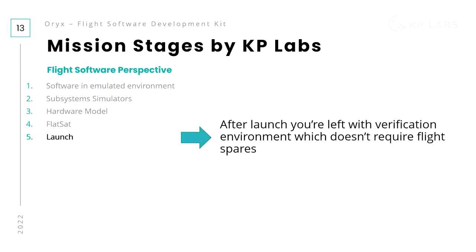So a very common approach is to have flight spares, but this is a very costly thing to do. Most organizations I know cannot afford having a flight spare lying around for 5 years. Even if they have a flight spare, they will use it probably for another project in a year or two, or it will fail to function when needed. With this approach, you get a fully capable test environment, even without the actual flight spares, because you have verified the simulators against the flight hardware.